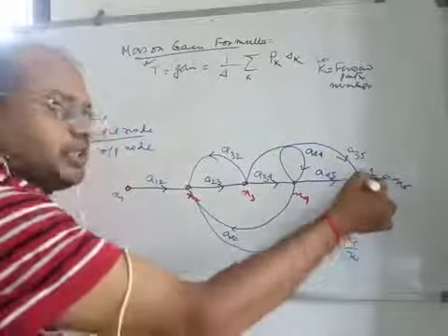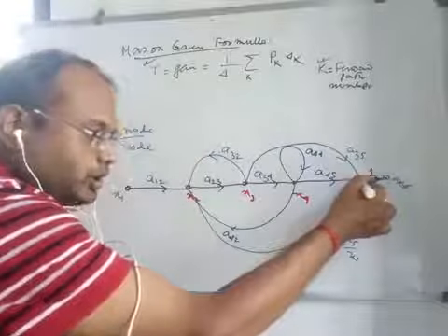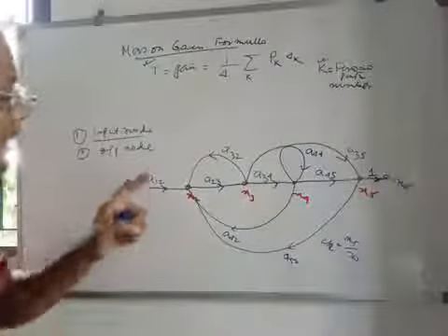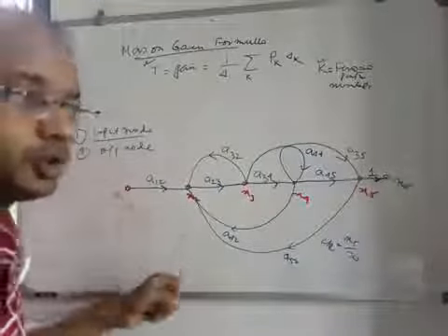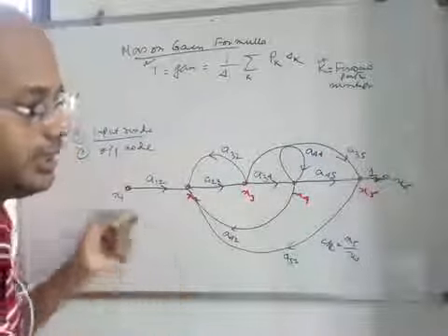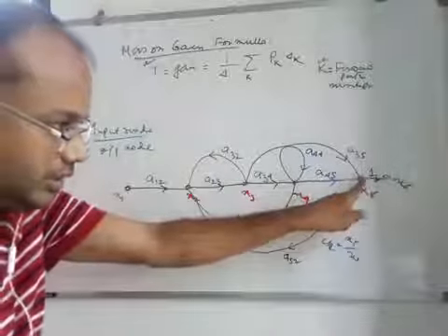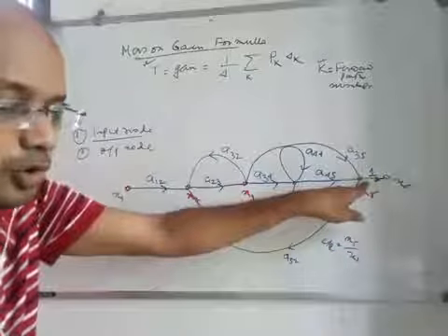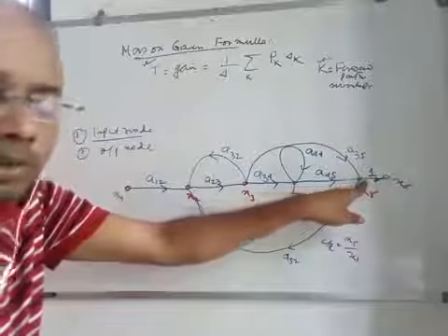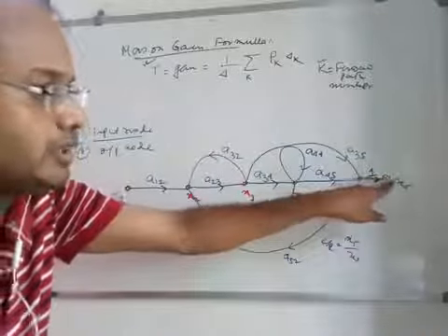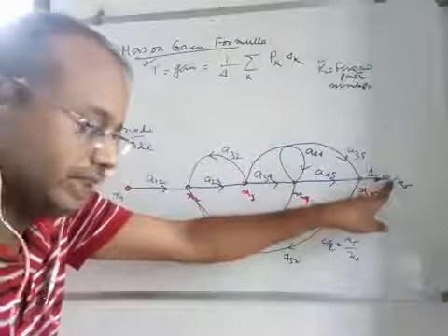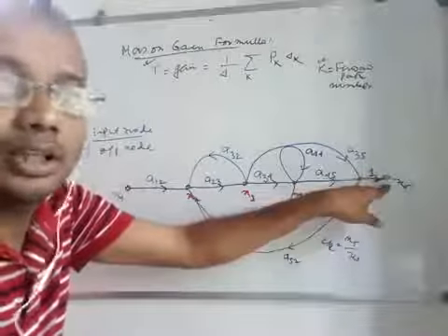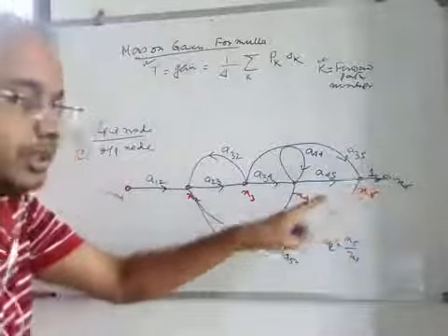If this is taken as the output node, that is also valid, but as we define the output node as the node where there is only the incoming branch, and this x5 has outgoing branches coming out of it, that is not considered to be the output node. So according to the definition, there must be another node x5, the same node, with a branch gain of 1, such that it has only the incoming branch, right?